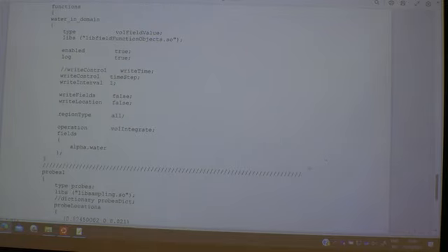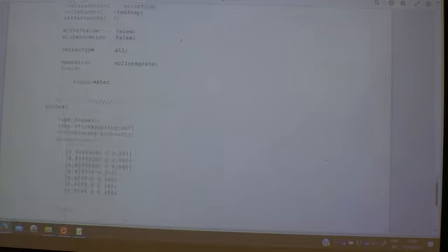Here also I have given you probes, the 8 different probe locations punched in, so you don't have to worry about punching in all these numbers. So that should be okay, I think. And then when you simulate, you will find these 8 pressure values, both for pressure and the pressure minus rho GH. Actually, you don't need that one, but that's another story. You need the total pressure. And then you'll find that one in the file, even Y plus if you want.